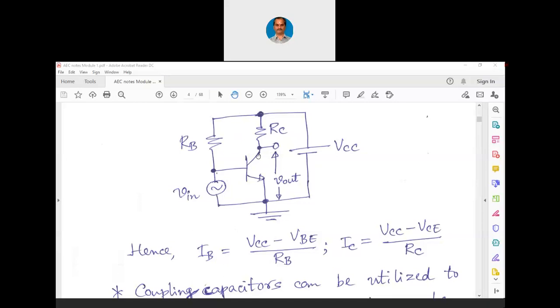So, this AC should not turn the transistor completely on or completely off, as I told you in the morning's class about the clipping issues or unfaithful amplification. So, for faithful amplification, DC is supplied only through the battery and only pure AC should be supplied. If any signal which is input to the amplifier contains part of DC, that DC should not be given to the amplifier.